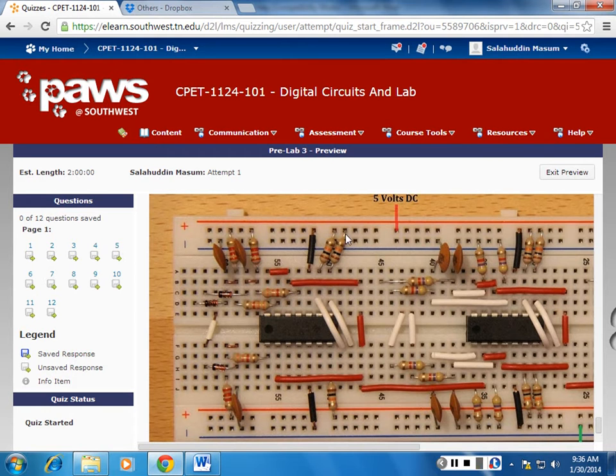This means all these things, like these two resistors, this black wire, this resistor and everything in the top row, are getting the voltage 5. You see what I'm saying? Because the top row is connected, all the holes are basically the same point. If you connect the voltage 5 here, everything connected in the top row gets voltage 5.